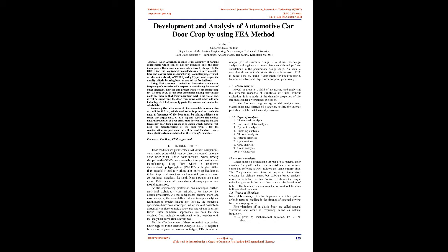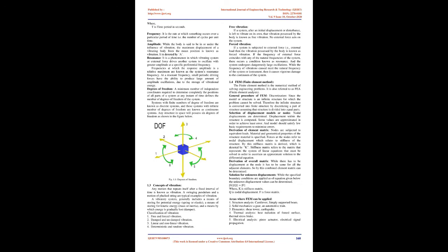1.1 Modal Analysis. Modal analysis is a field of measuring and analyzing the dynamic response of structures or fluids without excitation. It is a study of the dynamic properties of structures under a vibrational excitation. In structural engineering, modal analysis uses the overall mass and stiffness of a structure to find the various periods at which it will naturally resonate.